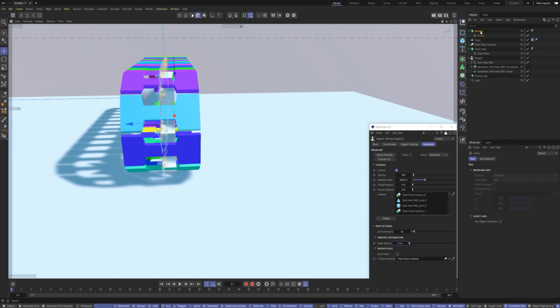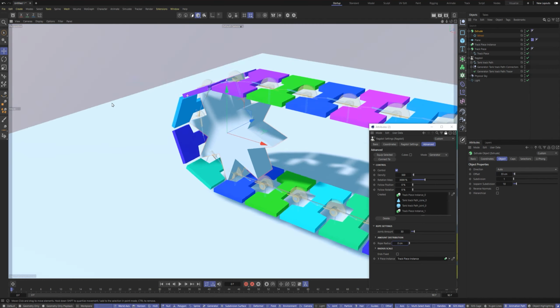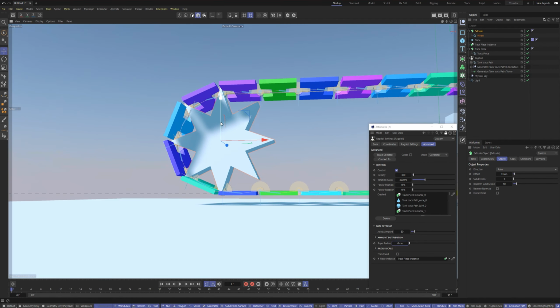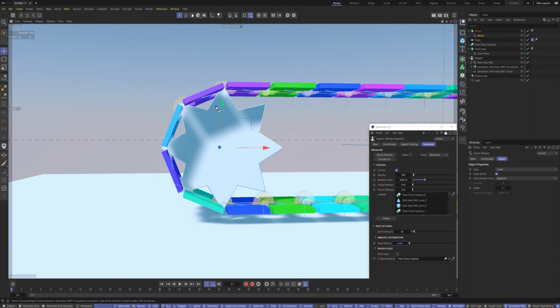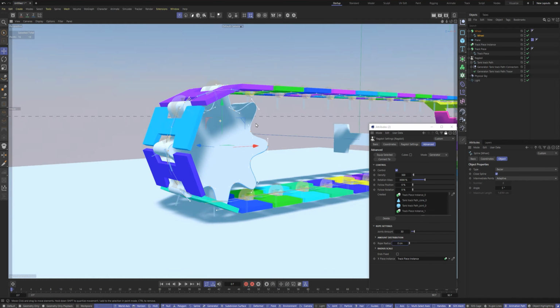Now let's create the rest of the tank's suspension structure. The main thing we would like to avoid during the simulation of the tank is tracks falling off rollers. The caterpillar particles must have a groove, and the drive gear must penetrate into the groove with its spike. Then the drive gear will pull the track. The number of spikes on the drive gear must match the number of holes between the track particles. The gear spike should not protrude above the track surface.